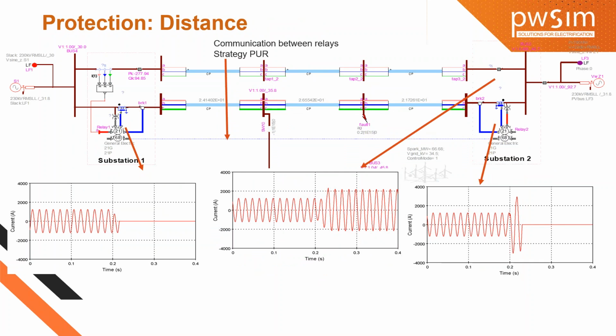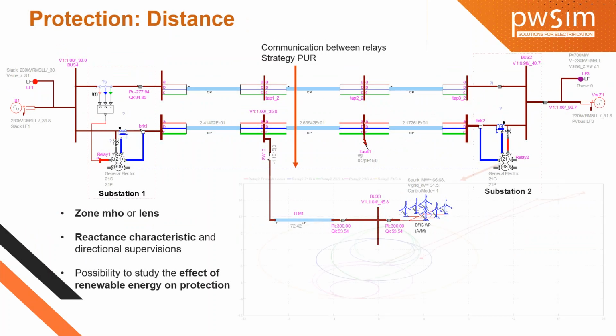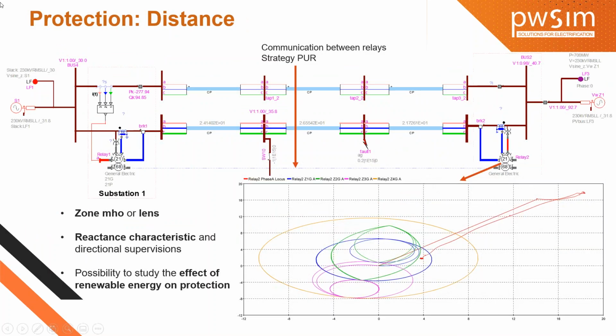Next one is the distance protection. In EMTP distance protection, we will find the RX graph also. Based upon the zones we have used, with 75% and 25% zones added in the different distance relays, we can go to the RX graph and create a fault, and we can see which zone the fault is located in, that is zone 1 or zone 2. Directly we can see it in EMTP software.